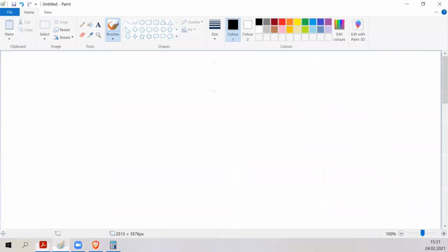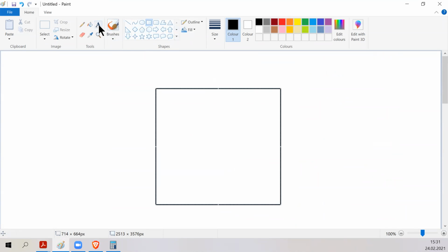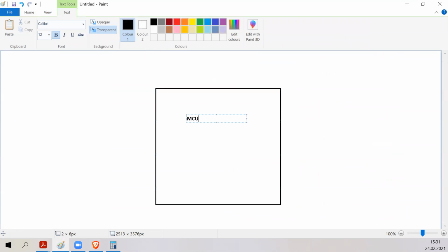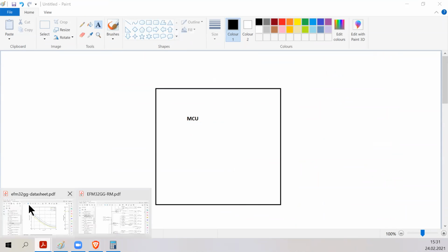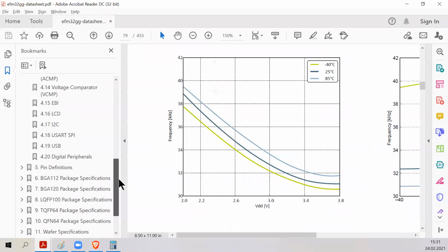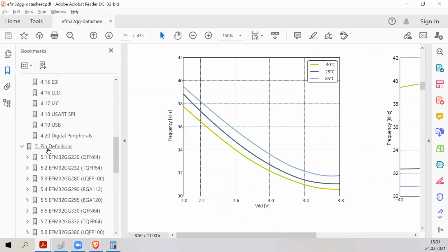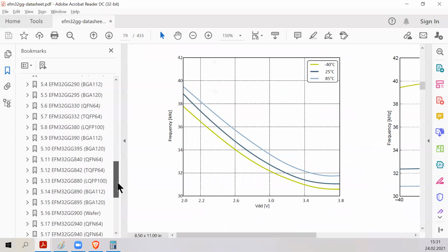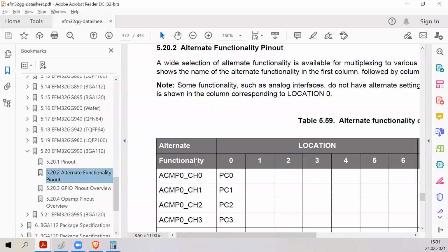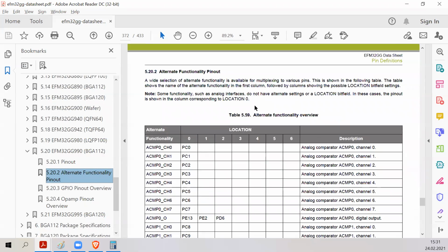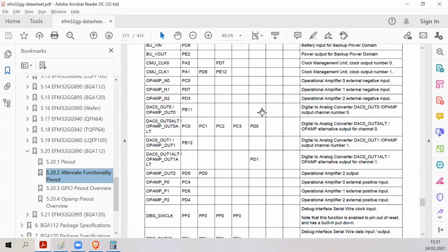And a little bit of information about how to connect an external oscillator to the microcontroller. If we check its datasheet, the microcontroller usually has special pins that normally are used as general purpose input output, but they have alternate functionality for external crystal connection.